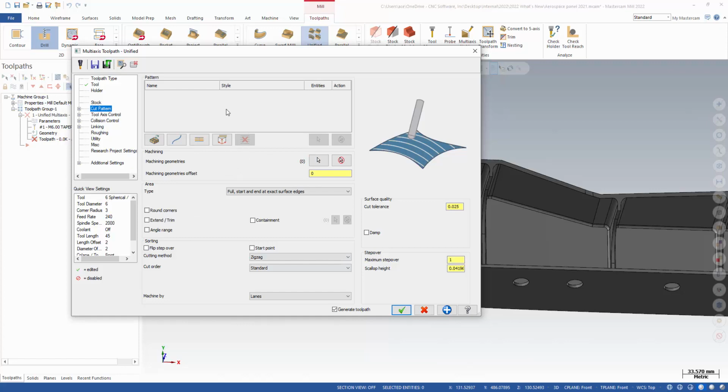So let's take a look at what this new interactive grid gives you. You're going to see some buttons along here that let you choose various types of input. Now, automatic will take the area that you've selected and try to figure out the toolpath that fits over it well. Curves gives you the ability to, say, morph between two curves or to be parallel to a curve. Surface is going to be the same thing.